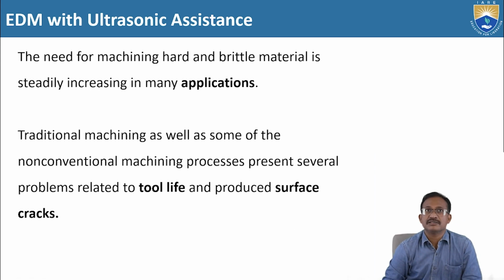So for this, EDM with ultrasonic assistance is best suited. In place of traditional and non-conventional machining processes, EDM with ultrasonic assistance is best suited for hard and brittle materials, and gives more tool life and good surface finish without surface cracks.